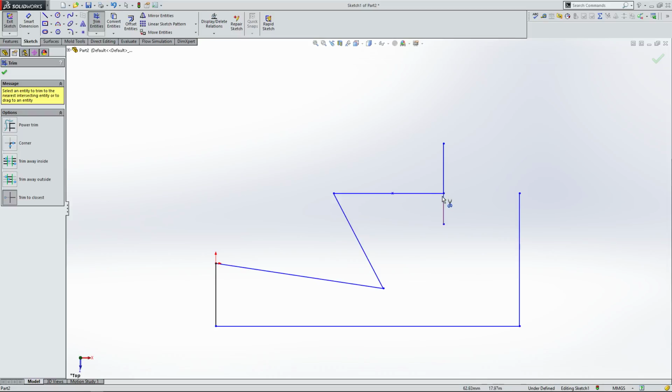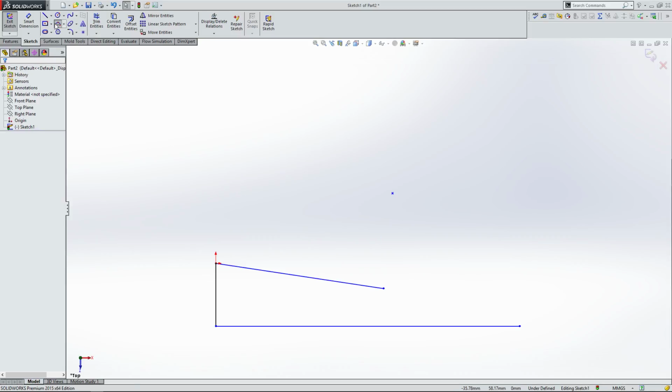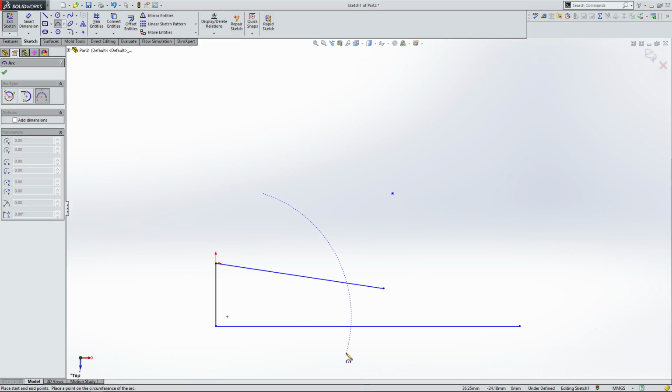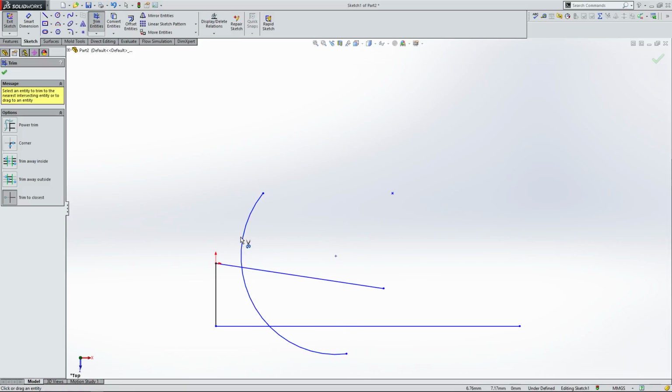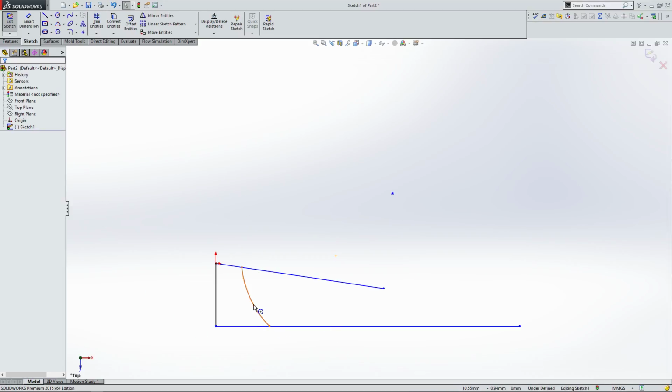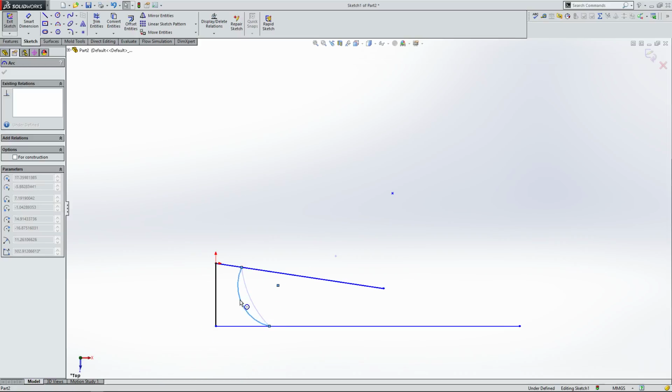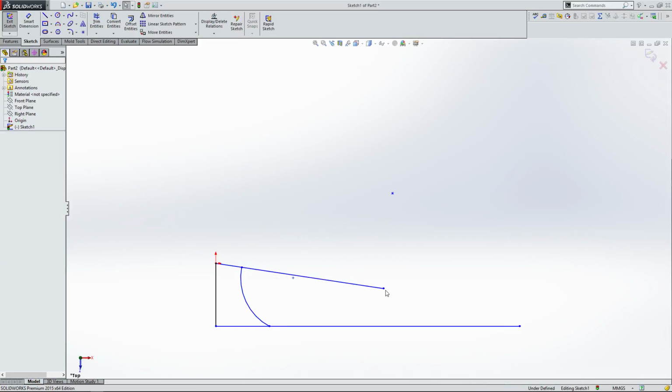Usually lines are often intersecting your design, so I can click on this, delete that, delete that. I can delete this whole line, delete this whole line, delete this whole line very easily with that tool. I can create a curve, and when it passes through lines, I can come up here to trim entities and just delete this, and now you can see that I have a nice curve inside here that I can use for whatever application.